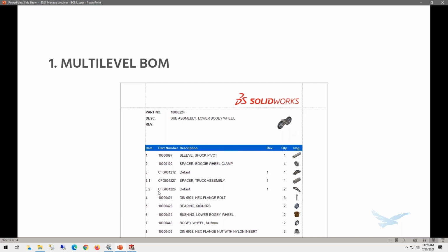One little trick to those when we're editing them: if you don't have an assembly that's super deep, like your assemblies are commonly 8 levels deep, you want a sample assembly when you're building this report that is 8 levels deep, so that you'll have all of the different reference levels to pull from as you're building it up. So it may be worth creating even just a dummy assembly that just goes really, really deep to do that.